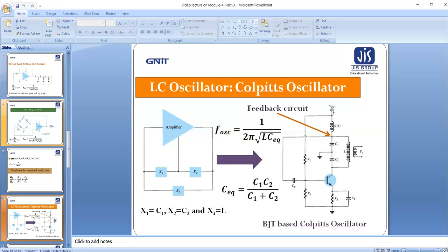So in case of the power line, if any AC from the capacitor tank circuit tries to mix with the VCC, the RFC will provide high impedance. So there is no mixing of the AC into the DC. But if we use a simple resistor, then a voltage drop will occur, and it will also affect the DC signal.